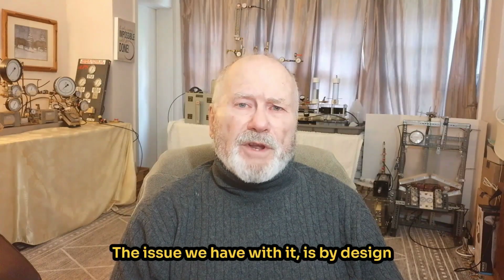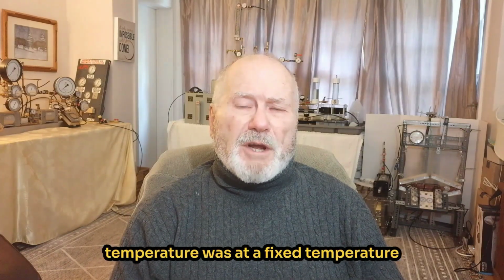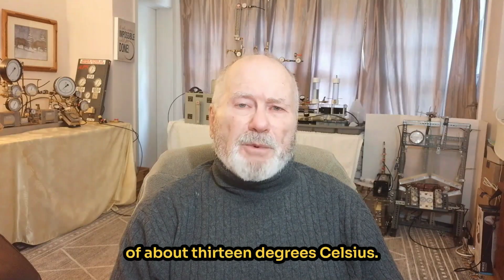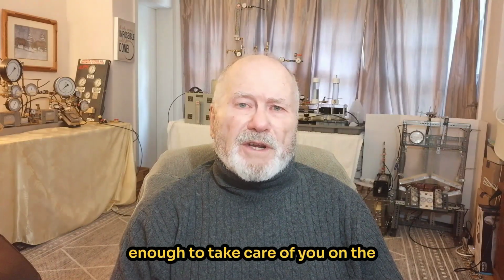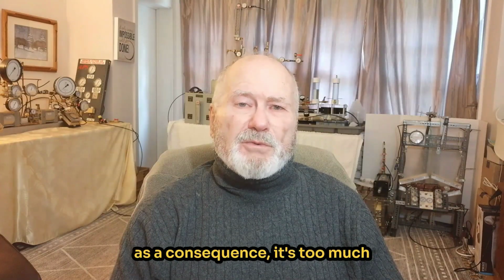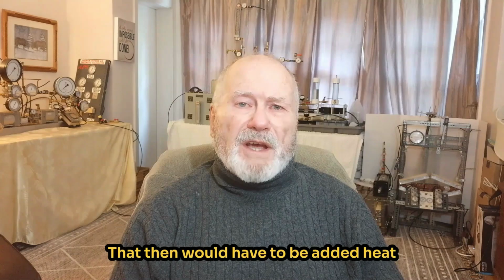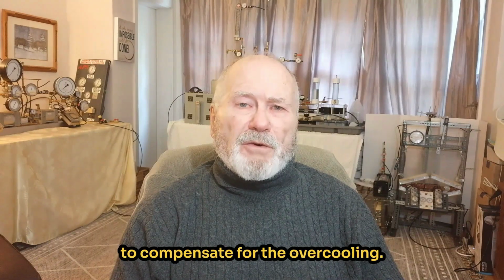The issue we have with it is by design from the early 1900s was that the temperature was at a fixed temperature of about 13 degrees Celsius. This is a temperature that is cold enough to take care of you on the hottest day of the summer, and so as a consequence, it's too much cooling for all the rest of the year. That then would have to be added heat to compensate for the overcooling.